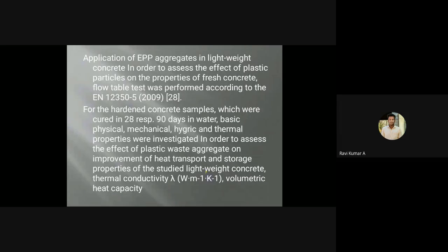As mentioned earlier, normal concrete can weigh between 140 to 150 lbs due to the presence of denser aggregate in their natural state. As a result, many believe normal concrete to be cheaper compared to lightweight concrete blocks. However, natural concrete requires additional materials for framing, cladding, and steel reinforcement. Ultimately, this increases the overall cost.